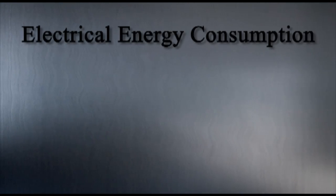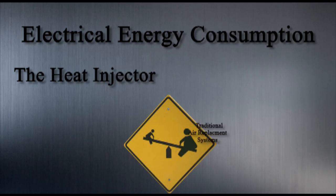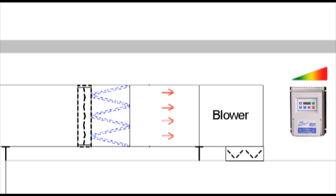Let's look at the electrical energy it takes to push the fresh air into the booth and compare the heat injector to the traditional air replacement unit. The heat injector removes the resistance of the burner and the profile plates, and by changing the speed of the blower motor, the resistance of the discharge damper is removed. This causes the blower motor to consume considerably less power.